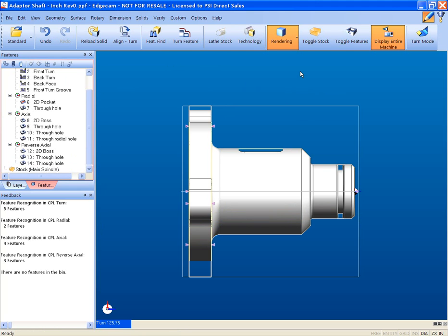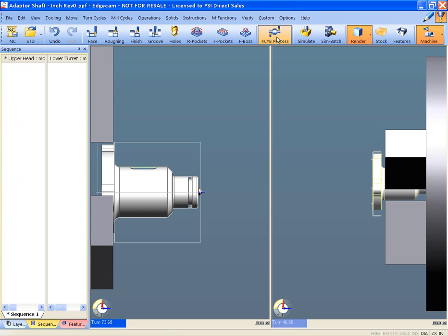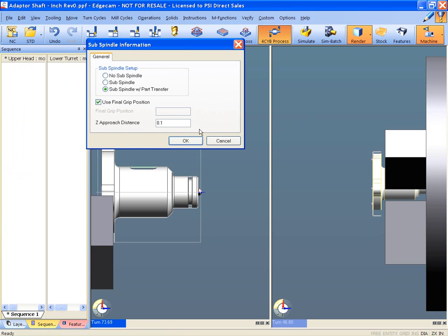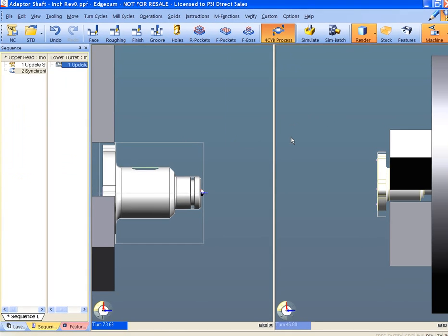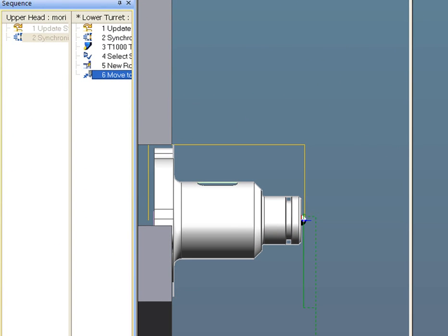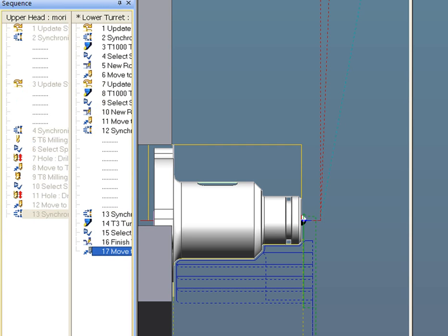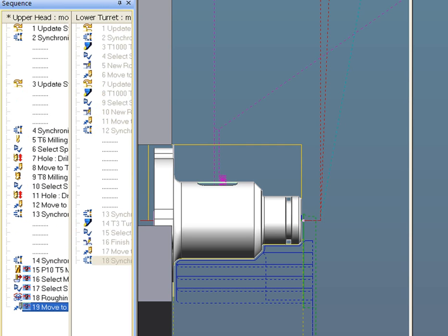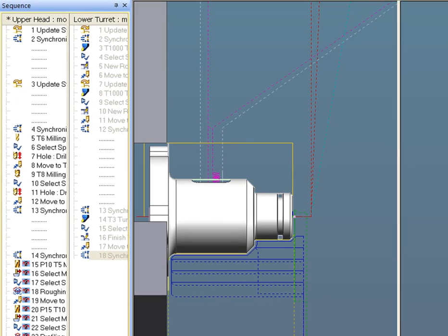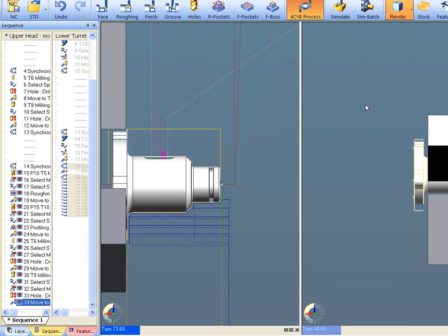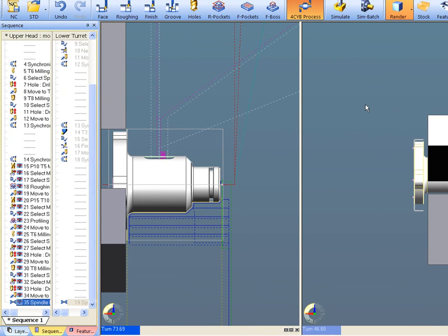The design intent of the solid is captured via the automatic feature recognition, which identifies the manufacturing features. These intelligent features carry the design knowledge directly from Inventor. This information then drives your machining decisions. The part has been loaded in a dual spindle, dual turret lathe. Which machine is not important, for Edgecam post-processors are the most robust and easily developed in the industry.